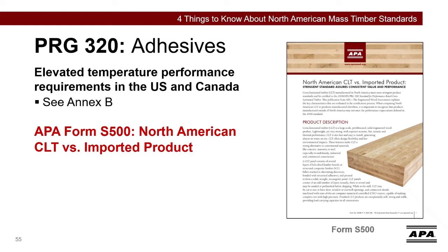If you are considering using imported CLT products, it's important to evaluate all characteristics closely. Products manufactured outside of North America may not meet these stringent standards of PRG 320 relating to adhesive heat durability, moisture durability, and overall fire performance.